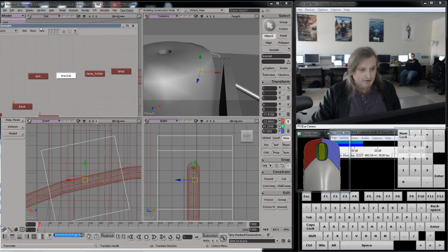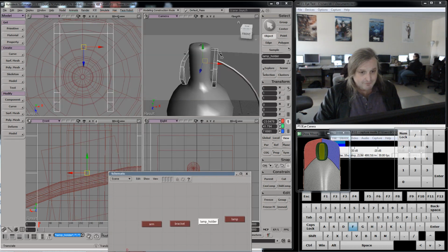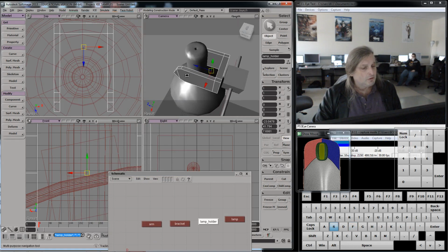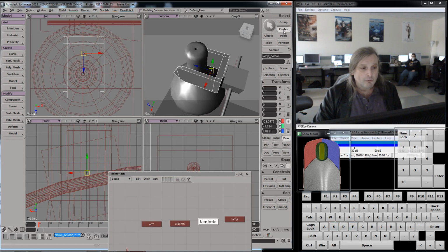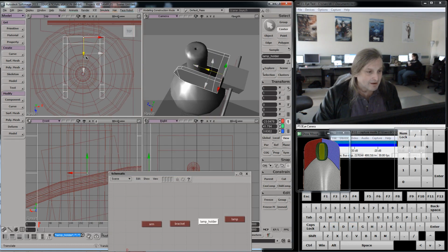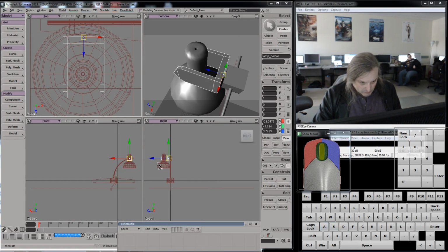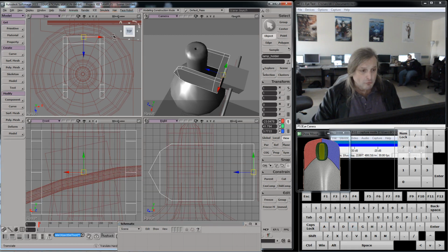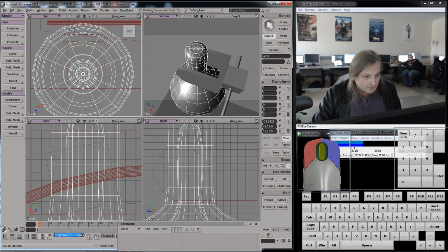But now I got to pick my lamp holder, which is going to be in the wrong place now. F, F, F. And we can see this over here. See, it's not touching? I need to make that touch, and I need it to rotate from back here. So let me move its center point first. I'll move its center point to the back of it right there. And let me see in these other views if that's okay. F and F. Yes, that's good. Now I'll move the actual lamp back so it touches that. Good. And now this, which is my lamp,